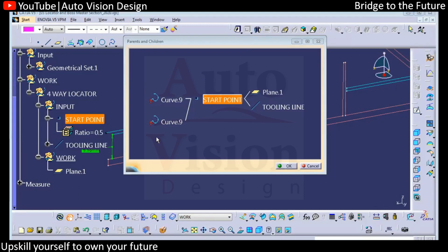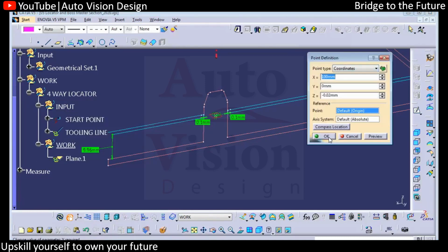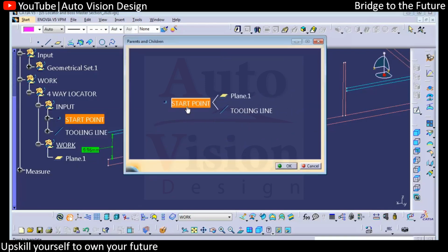How can we create that? We'll just right click and make it isolate. We'll isolate that point, double click, and go for the coordinate. Whatever the coordinate is, you can just click OK, so it will get updated. Now you can check: right click, properties. So this point is now parametric.